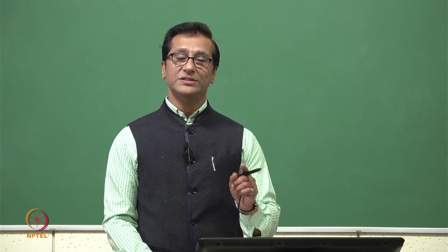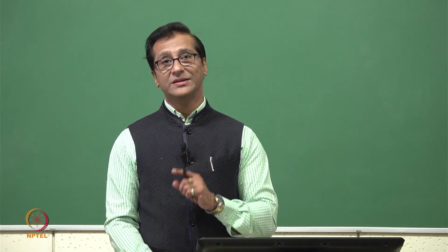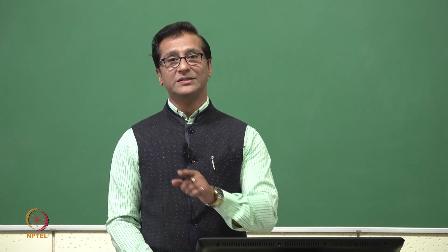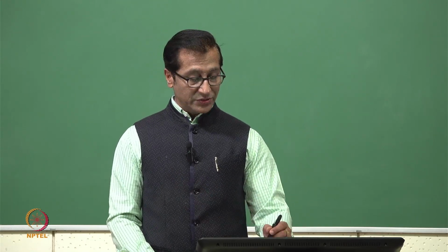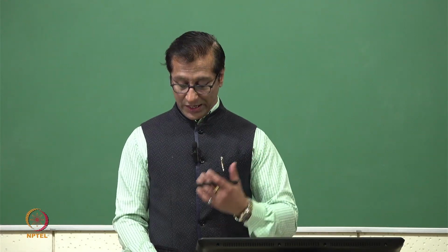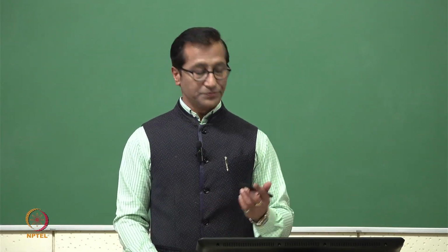And then the corrosion is increasing, changing the bearing clearance, increasing the temperature, and the increase in temperature causes further corrosion, which again changes the bearing clearance. So quite possibly a certain failure may occur in this situation. So we need to see how to really accommodate this kind of corrosion and reduce the operating temperature.